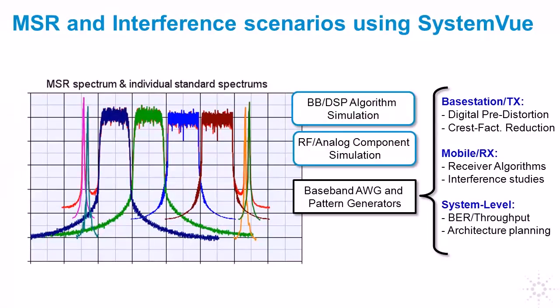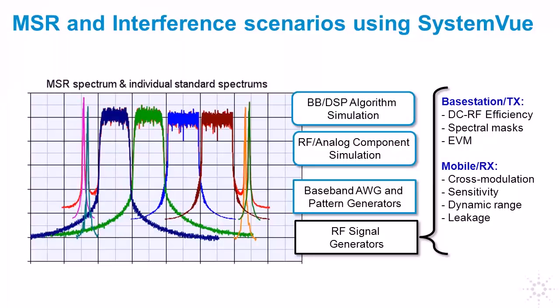These can also be used in a DigiRF sense and in a logic analyzer sense to provide test vectors for embedded DSP and DigiRF applications. Waveforms can also be downloaded into RF signal generators that allow, again, hardware component tests comparable to the simulation-based tests done with EDA tools. In this way, SystemVue provides symmetry between the simulation and measurement world for true model-based design.